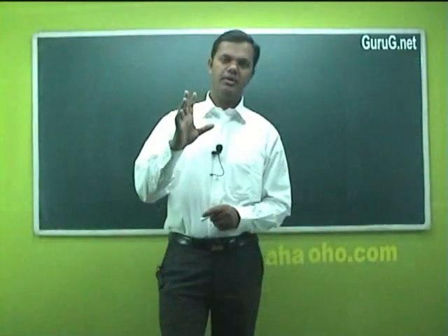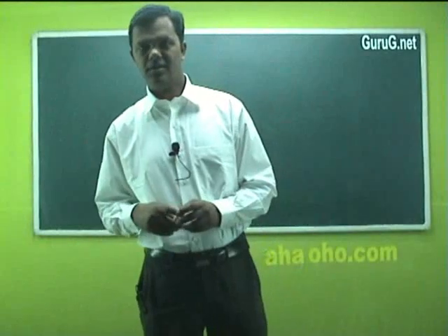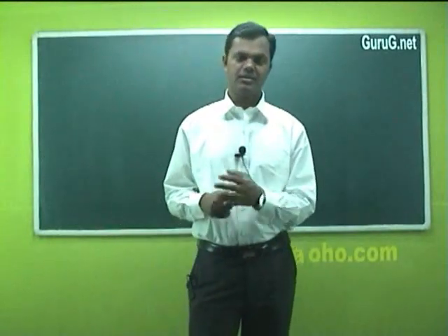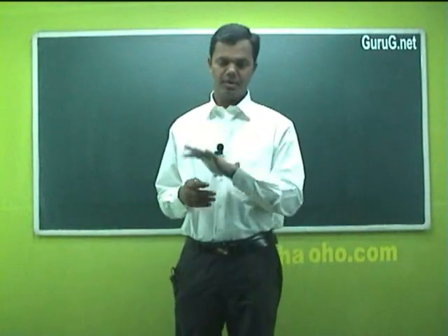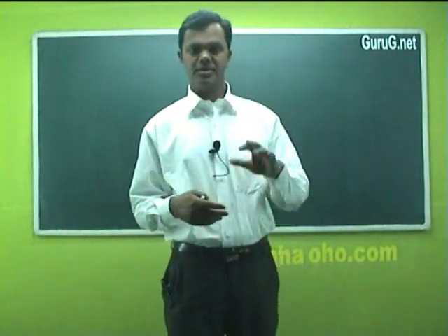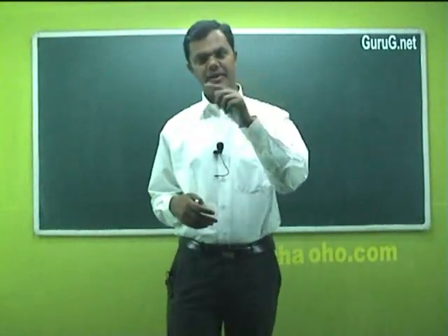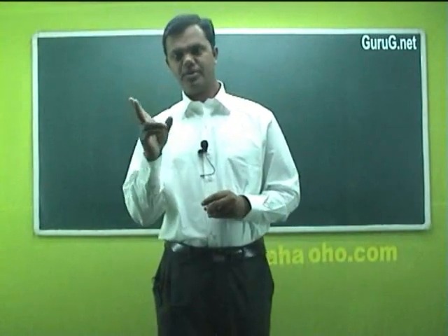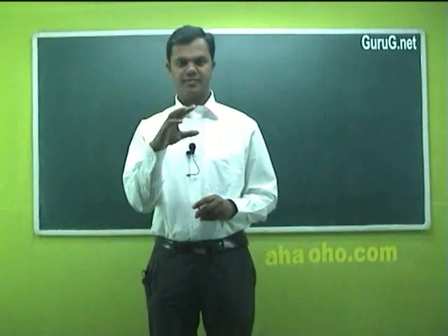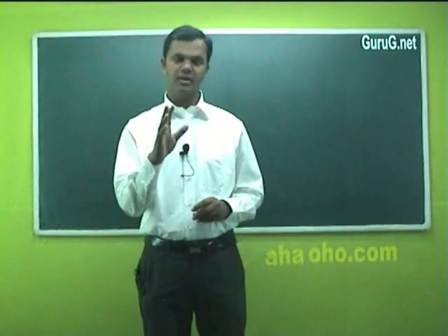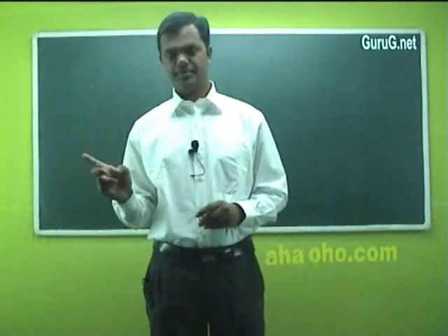So in unit number 1, we have seen the basics of statics and some of the problems when a number of forces are applied to a body. We have just covered how a force, even if it is in an inclined position, is converted into two components. That means a single force is converted into two components in the x and y direction, or horizontal and vertical directions, in order to get the resultant force.